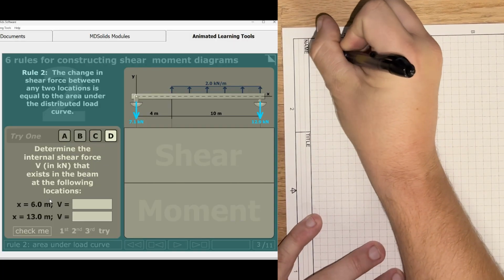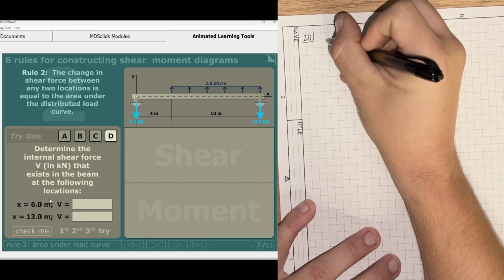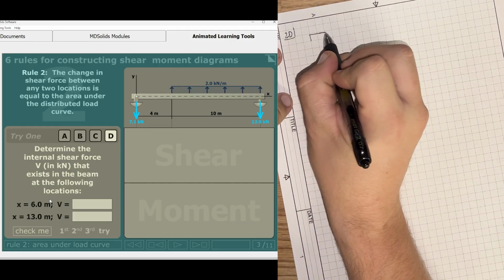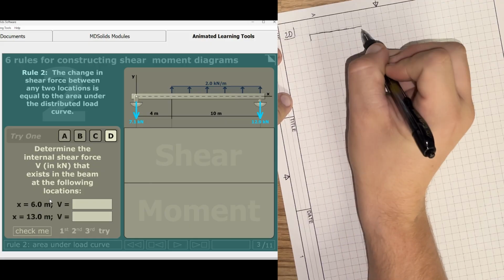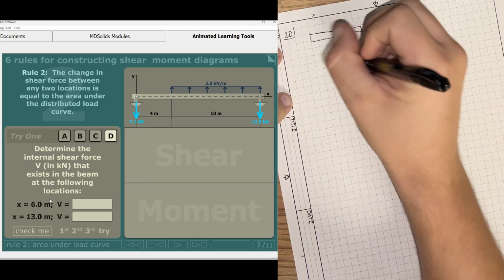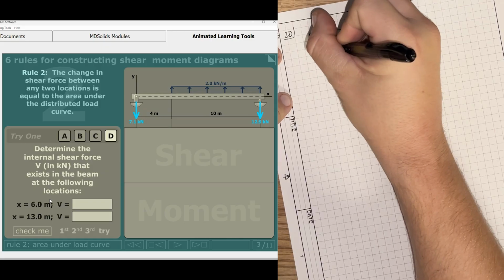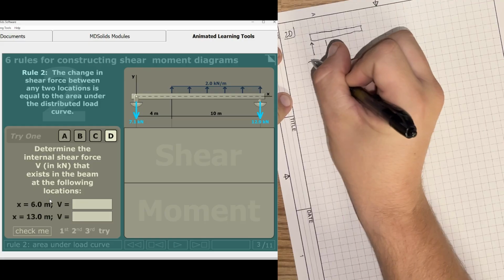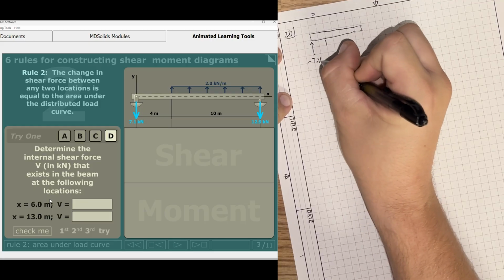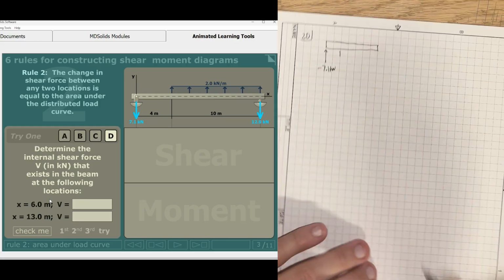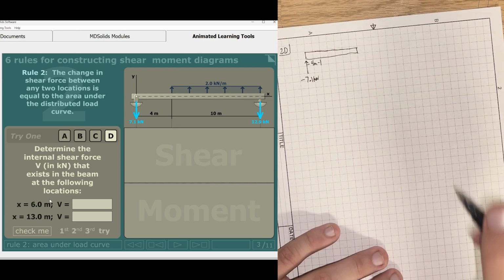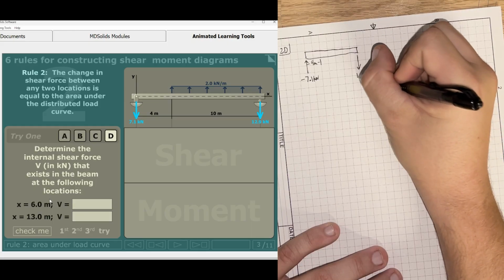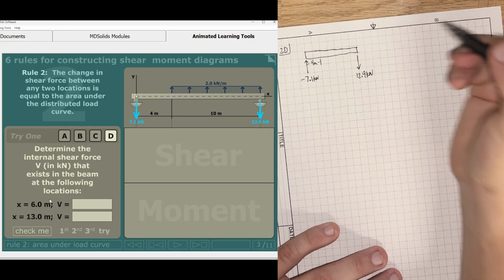It is going to be the case for 2D here that we've got this beam. Let's go ahead and set up our scale. 1, 2, 3, 4, 5, 6, 7. We're going to go in 4 here. So this is where this force is acting. Oh, and sorry, we can put this as negative 7.1 kilonewtons. Remember, that's just meaning that it's going the opposite way. And so this is 4 meters here. And then this guy is going to be occurring for the 10 meters. And I'll put this guy as the actual 12.9 kilonewtons.